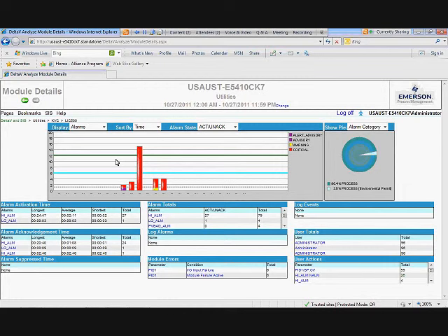One thing about this high alarm is I noticed that on this particular day it activated 27 times, the shortest time being just a 2-second activation and the average being 2 minutes. I suspect that this alarm is actually chattering. I'm also concerned that this alarm is even critical. Knowing that solvent area, I wouldn't have expected it to have been prioritized quite that high. So we're going to focus on the LIC 500 module.